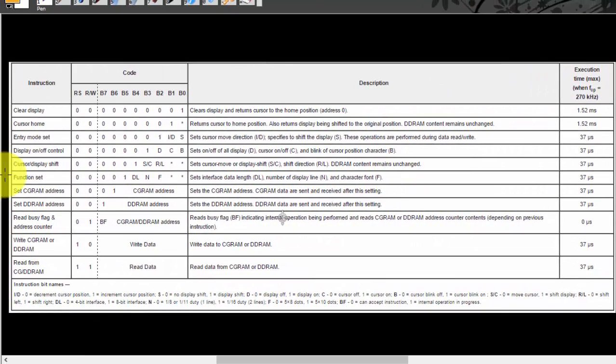Here you go. What you can observe straight away is this register select line. All of these are commands. This command clears the display. This command takes the cursor to the home. This will be discussed at length, the entry mode set, and then a few other commands. The register select line is always 0 in all these commands, which means these are all commands that we are transmitting. You can see that it becomes 1 only once or twice.